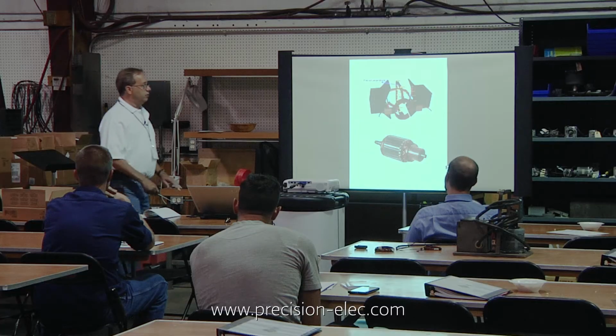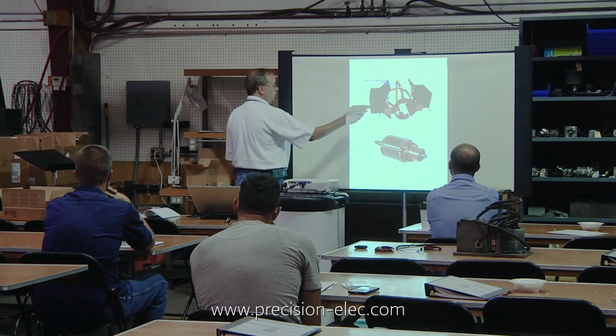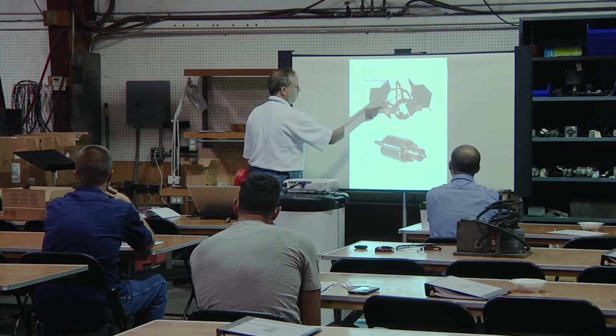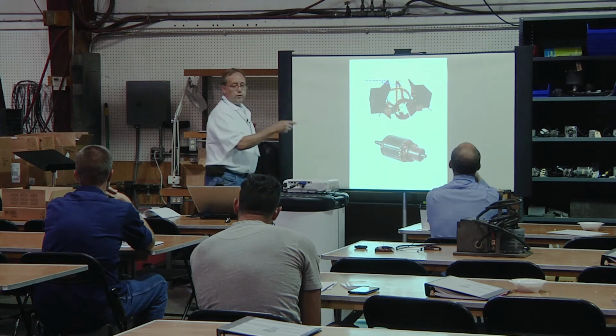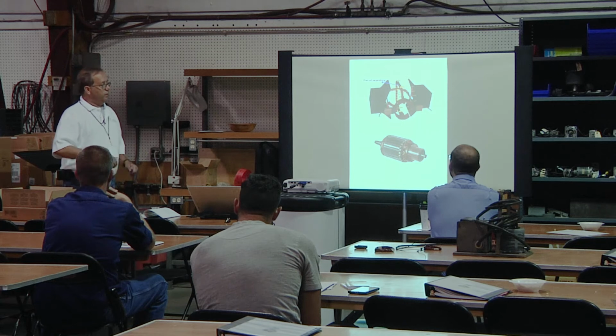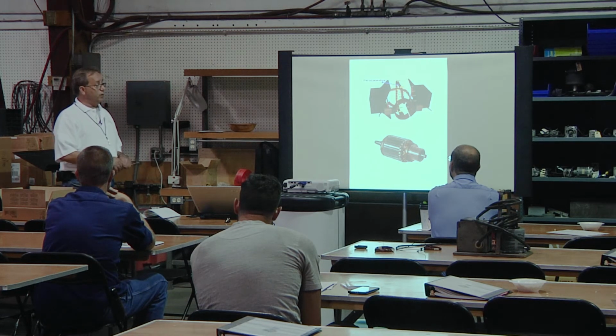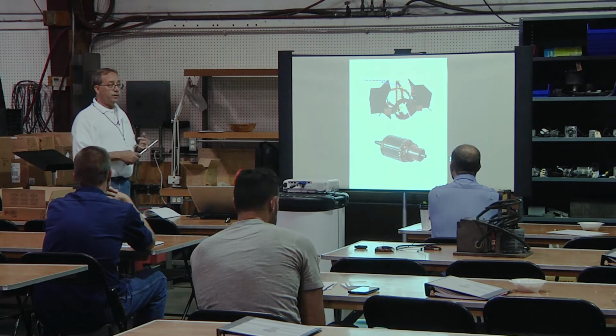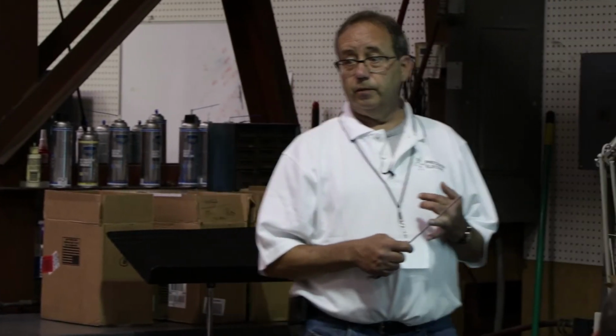The thing to do is, what controls the strength of these fields is that coil that's wound around that pole piece. Do you got enough current there? If you got enough current, maybe you've got shorts in that winding that's affecting the field strength. Amps times turns determine the strength of that field.